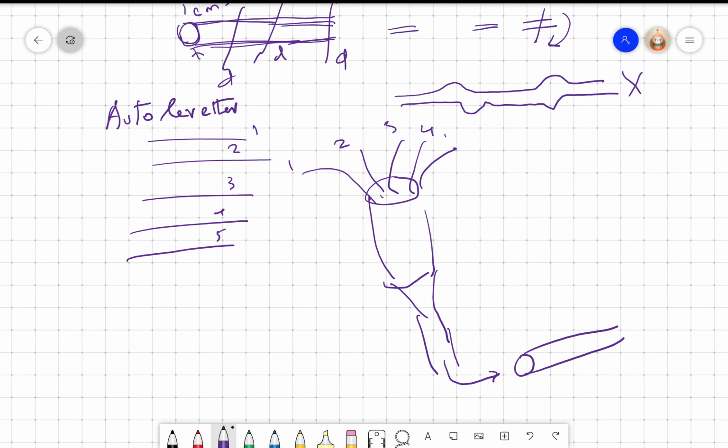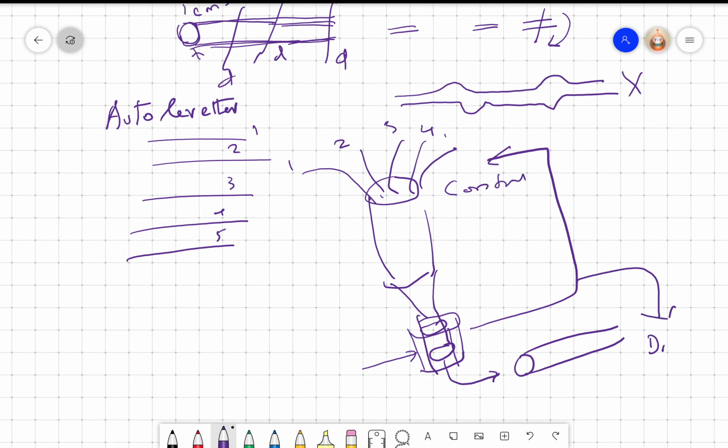The speed at which you draw is also controlled by putting a capacitive sensor here. So what you do is you put a tube around it, and if the amount of cotton is high, of course your capacitance will be high. If the amount of cotton is low, your capacitance will be low. So take the value and control the input as well as control the draw speed, right?